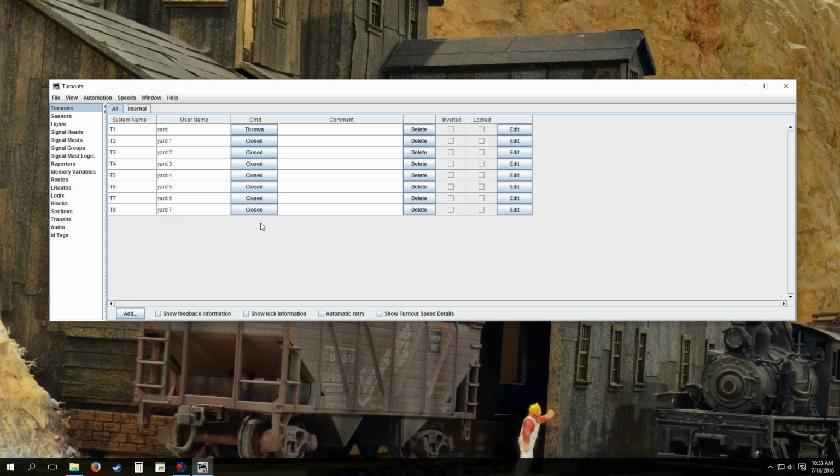So you ensure that these match. Just a little heads up here. If they don't match, there's two ways to fix that. One way is you can, of course, flip the wires if you're using a Tortoise or anything like that. You simply reverse the wires and then it'll be in the right position. Or if you're using a servo, you simply reverse the servo motor positions and voila. Although they're programmed, so just be aware that you might affect that somewhat.